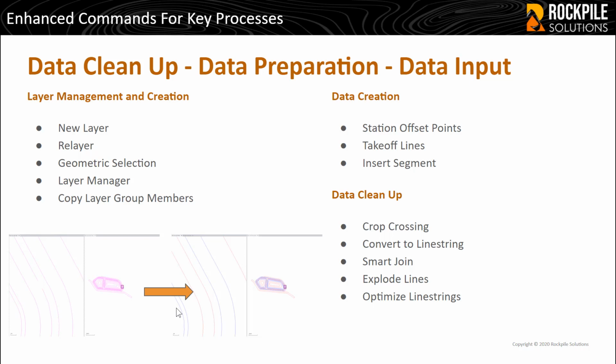Our new layer command combines not just the creation of the layers, it also combines the creation of the layer groups, and it allows us to define the takeoff properties for the categorization, but also which site improvements might be applied to those lines on those layers, but also how those layers are going to be used for design or existing in the takeoff process.